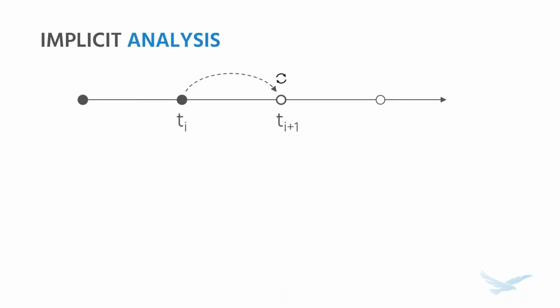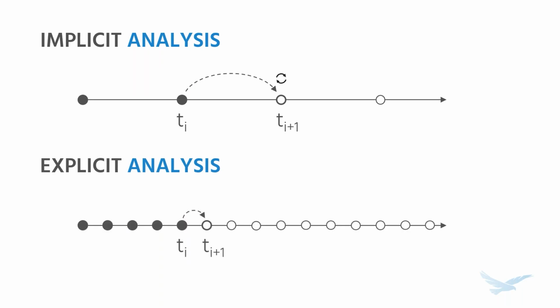Now, back to the time increments, we discussed how we go through, we increment, and we iterate. And this process is what's known as implicit analysis. We do also have something called explicit analysis. And the difference here is that in implicit analysis, we do those equilibrium iterations to make sure that we have an accurate converged result. In explicit analysis, there are no equilibrium iterations. And so by removing that, we get rid of the force balance problem. We no longer have to balance that equation.